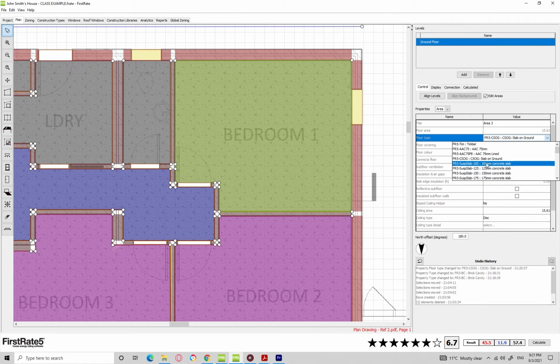I will say just pick one that you believe is accurate to what your floor is. For example, if it's timber, you have timber there. Don't be confused, by the way, you might see a timber vinyl finish, for example, on a floor, but that could still be a concrete slab underneath it. But the knocking exercise should give you some information. Sometimes just walking through the house will tell you what the material is.